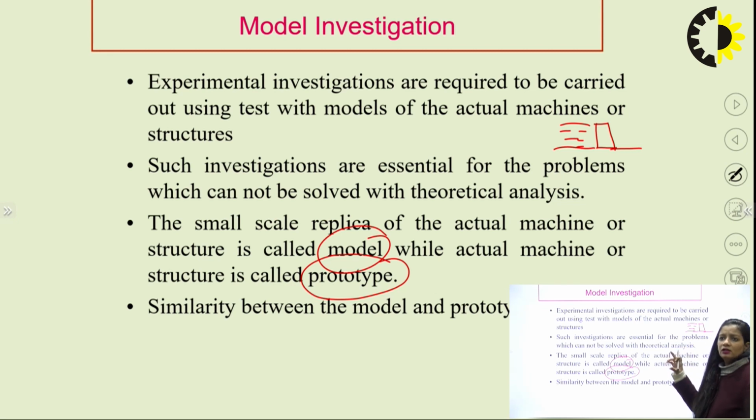Whatever the height of the particular dam we have designed, whatever the width of the particular dam, what are the dimensions, we need to convert that prototype into a smaller model form, and we need to perform some experimental investigations in that particular project, so that we can analyze whether the safety features are good or not, and whether that particular dam does not get destroyed under the water pressure. So this kind of investigation needs to be verified first.